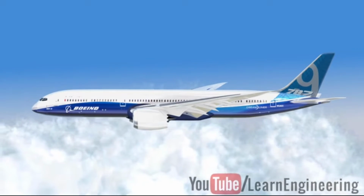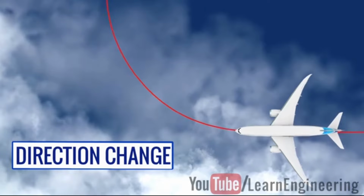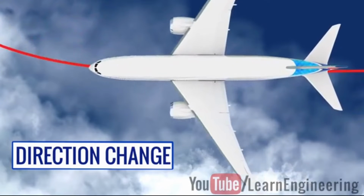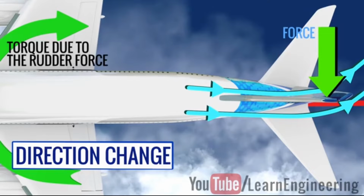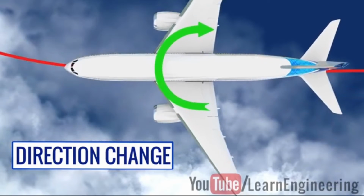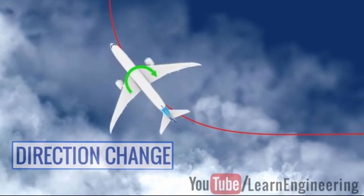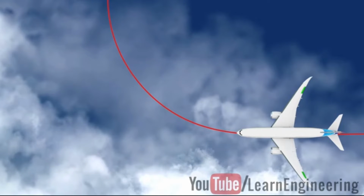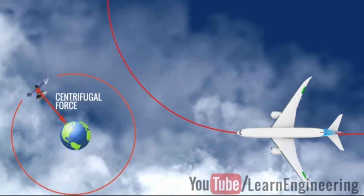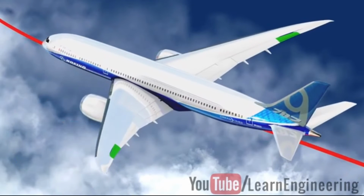Now, let's discuss the most crucial part. How does an airplane change direction? You might think that just by adjusting the rudder, you would be able to do this. The rudder produces a horizontal force, and this force can turn the airplane. However, such a direct change in direction will cause discomfort to passengers, and it is not a practical method. To make a turn as shown, what you need is a centripetal force. Let's see how pilots achieve this force.